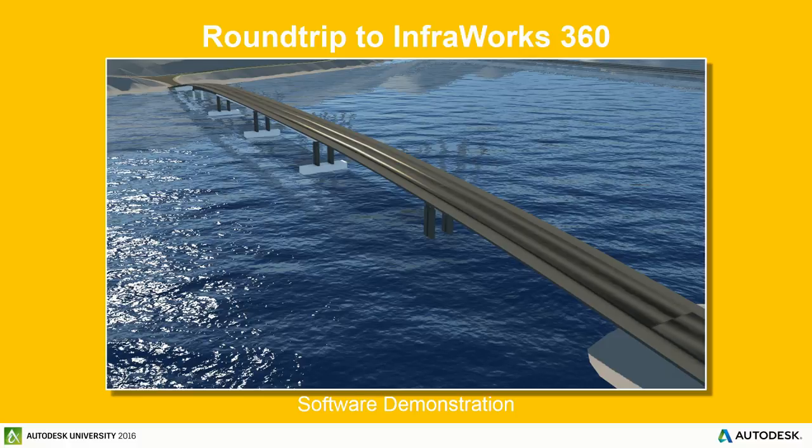Now, if you're using Civil 3D, for example, to do that, that's a bit more accurate. And again, you can use, for example, Dynamo to pull that data out, and then from there, bring it into Revit and keep, for example, the profiles perpendicular to the alignment, things like that.